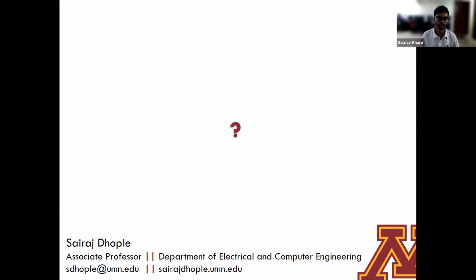Just like when we're inserting the PV, PV basically doesn't insert inertia into the system, especially if we are inserting the PV and not backing it up with an energy storage system. So in that case, the inertia is reducing. So is there any limitation, based on the controllability of the system, on how much PV we can insert?